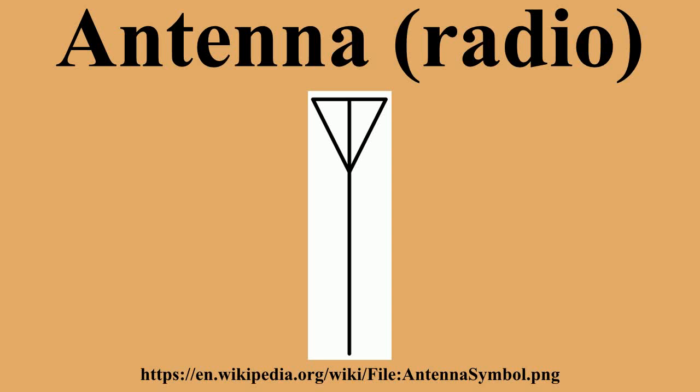An electromagnetic wave refractor in some aperture antennas is a component which, due to its shape and position, functions to selectively delay or advance portions of the electromagnetic wave front passing through it. The refractor alters the spatial characteristics of the wave on one side relative to the other side. It can, for instance, bring the wave to a focus or alter the wave front in other ways. Generally, in order to maximize the directivity of the antenna system. This is the radio equivalent of an optical lens.